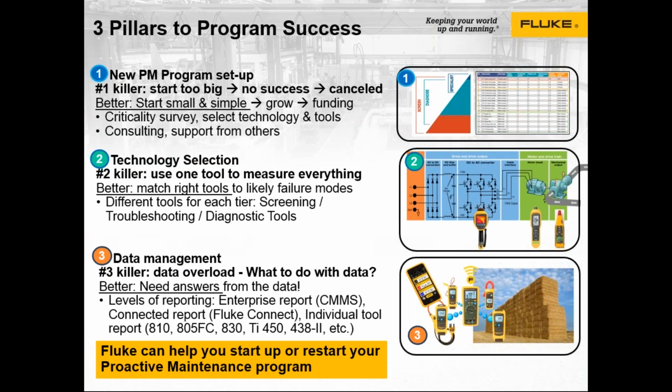But you're exactly right. Instead of just buying one tool, like, for example, a thermal camera and trying to just run your whole predictive maintenance program off of one tool, think about what are your failure modes in your plant. You know, I see a lot of bad bearings, or I see a lot of coupling problems, or I see a lot of electrical connections or a lot of overheating. That's going to help you figure out what tool you need.